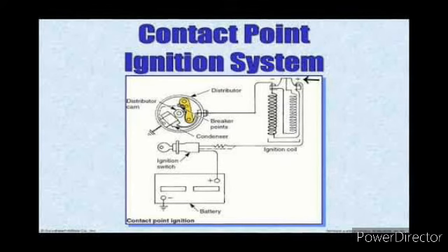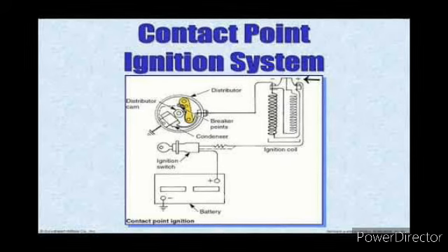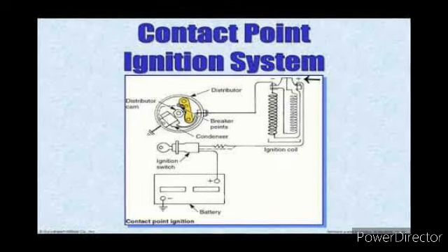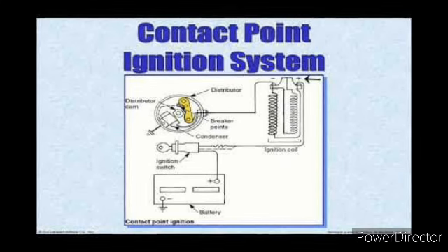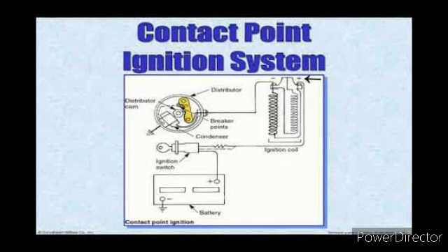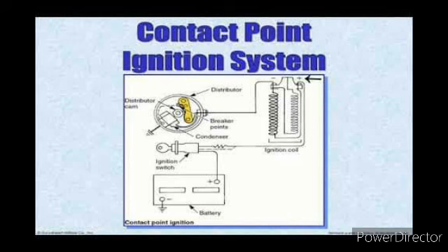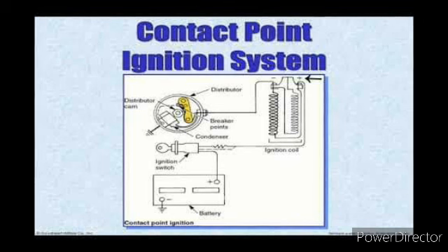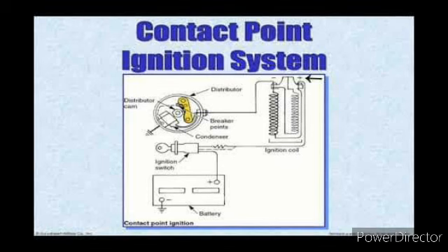On most engines, ignition timing is set by loosening a distributor hold-down bolt and rotating the distributor to advance or retard the spark timing. Old-time garage jockeys used to set timing by ear, turning the distributor until the engine sounded right. Most mechanics use a timing light that takes a signal from a spark plug wire and releases a pulse of light every time the spark plug wire has electricity running through it. The light is aimed at one of the pulleys on the front of the engine, and the distributor is rotated until a notch on the pulley lines up with the mark on the pulley guard.